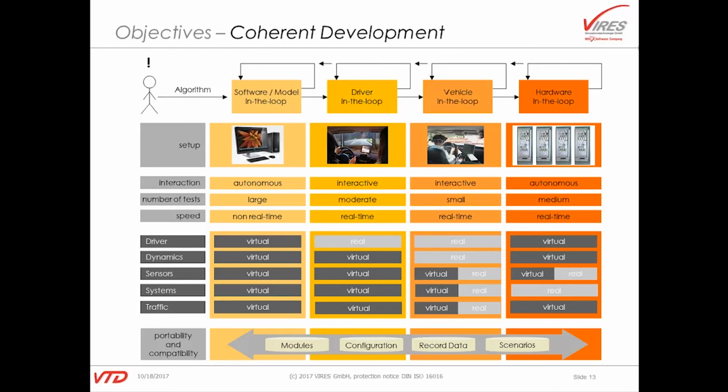More interesting, maybe for you, is the hardware in the loop test environment, which means that we will be feeding actual hardware with data that has been generated within our environment. So the sensor layer becomes very important, and the systems, of course, that are under test will, in this case, be the real systems, like, for example, an ACC control box. Okay. These are the environments.